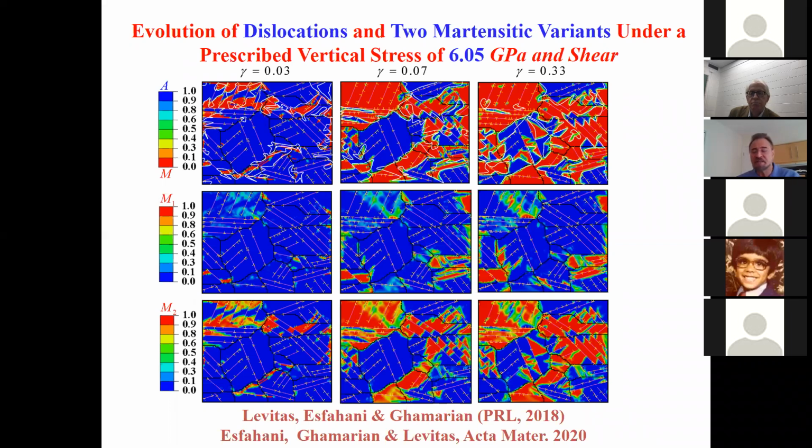Let's put it this way. All that you want to say about shape memory alloys is a stress-induced phase transition. This is stress-induced, not plastic strain-induced. If you start a plastic strain-induced phase transition in shape memory alloys, you will spoil the effect. So this pseudo-elasticity will be destroyed.